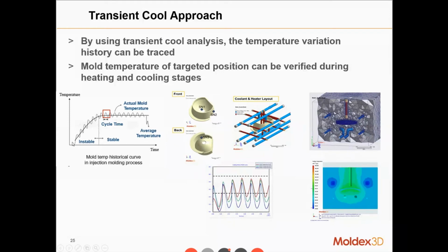And you can see from the start of injection, you experience an unstable temperature rise, and then you transition into the stable phase. So two approaches we use here in Moldex. The normal one is the average temperature.